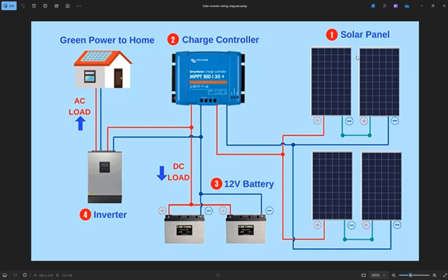It should be a little bit higher, because whenever you regulate it to stabilize it to exactly 20 volts, you get some loss. So 22 volts DC, for example, after the rectifier, and then you regulate it to exactly 20 volts for your laptops. Eventually you get a very stable 20 volts, not damaging all the sensitive electronics inside.